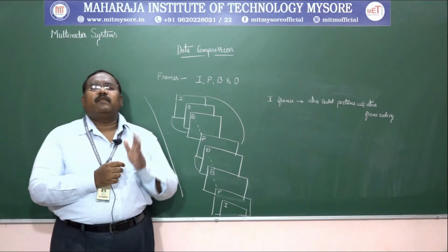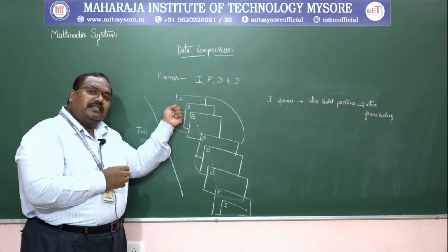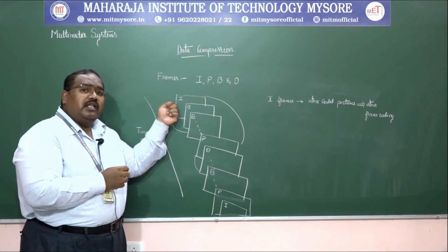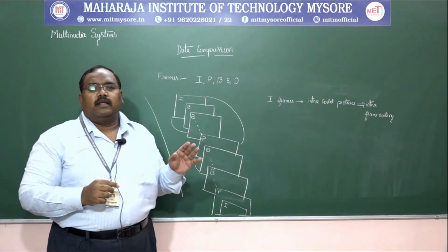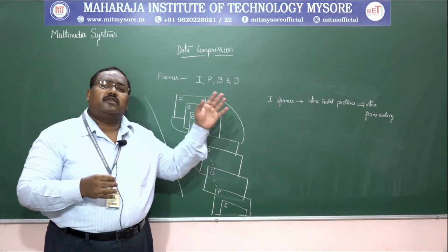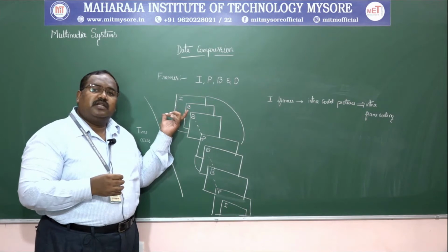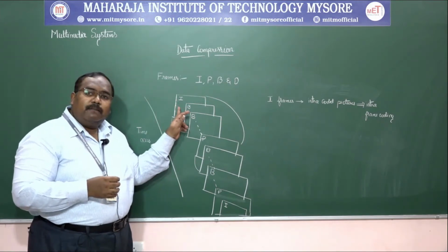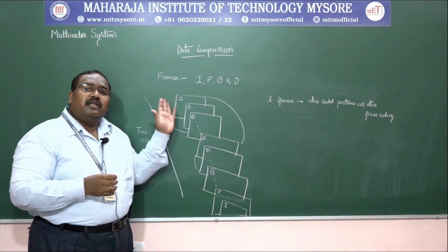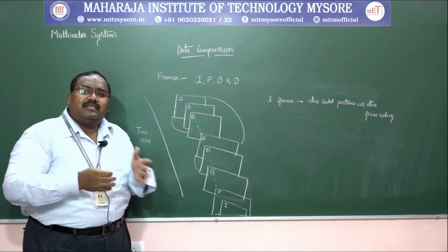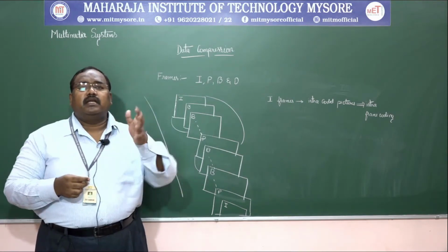Here when we talk about MPEG, it falls back on the results of JPEG, because we are using a still image here. That's why we are using the compression techniques that are also associated with JPEG. You might be asking, sir, why do we need to have the standards of JPEG and also H.261? Now the requirement of still image compression technique comes into the picture, because this is an independent frame. It has not been derived from any other previous frame, or no information is derived. So it can be treated as a still image itself. So that's why some of the characteristics of JPEG have been derived here.